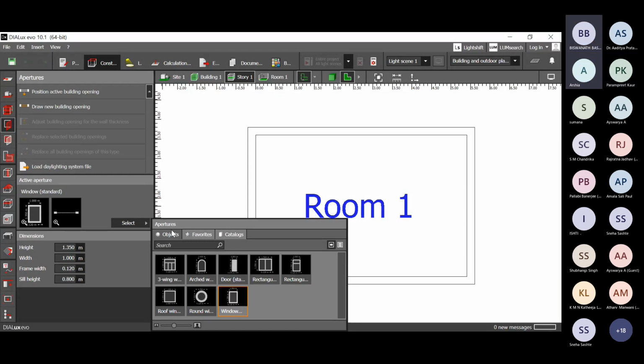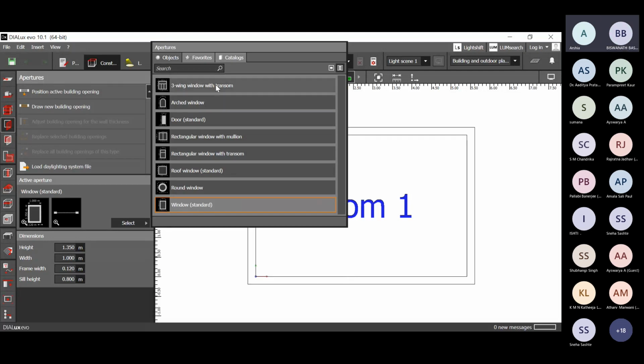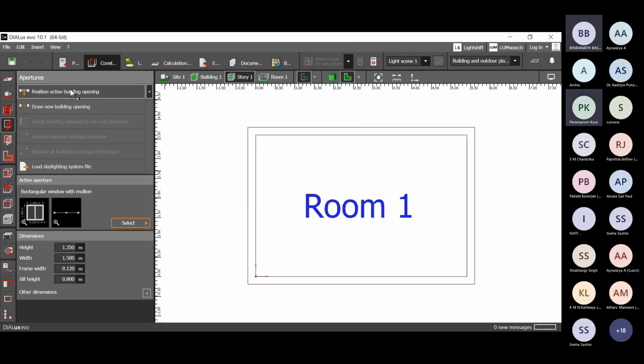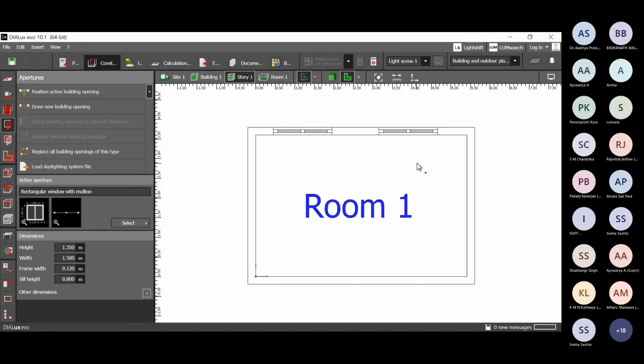I've been able to delete it, but can't move the window. So I tried to right click on the window and then I had a few options, and with the help of that I tried to move it. Yes, that may be possible. Normally, it positions the window with respect to its center point. Many a time it so happens that it interferes with the left or right wall. So after you place it, we can always position it back. Yes, on right clicking, you are getting that option. Options are coming: move, rotate, and scale. So I believe that we can do that directly.